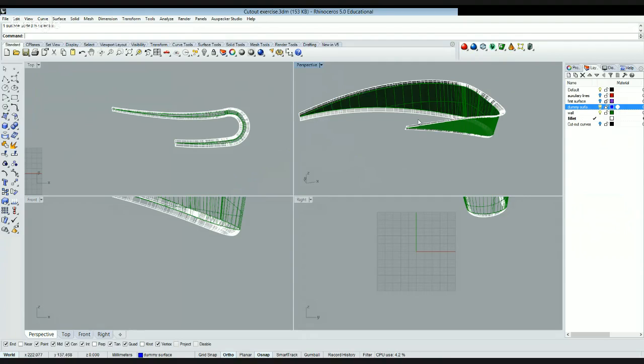So I'm going to create a new layer. I'm gonna name it floor. And I'm gonna put my floor here. Okay, and I'm gonna turn off my dummy surface. Okay, so I will use the command extend. Enter. And I will choose the type smooth. I will press enter for dynamic extend, and I will select now the bottom edge of my fillet here. And I'm going to snap near to the end of my floor surface here.